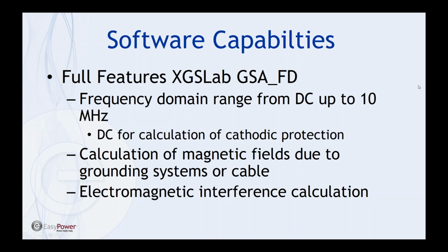Generally, these other facilities end up being buried pipelines or other buried electrodes nearby. But the fact that you can calculate the induced current and potential due to the resistive, capacitive and inductive coupling is helpful in many situations.